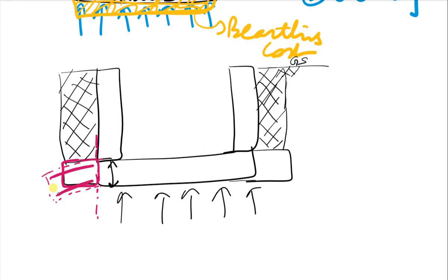We provide reinforcement in this case also, because sometimes there is a reversal of stresses when the tank is unloaded. To account for that, we provide equal reinforcement in both faces. Similarly, the next critical portion is the center of the raft, where we will calculate all the moments and loads and find out the critical moment.